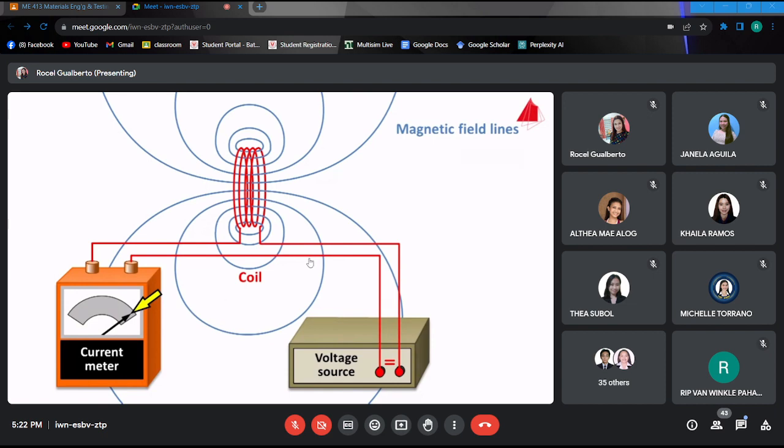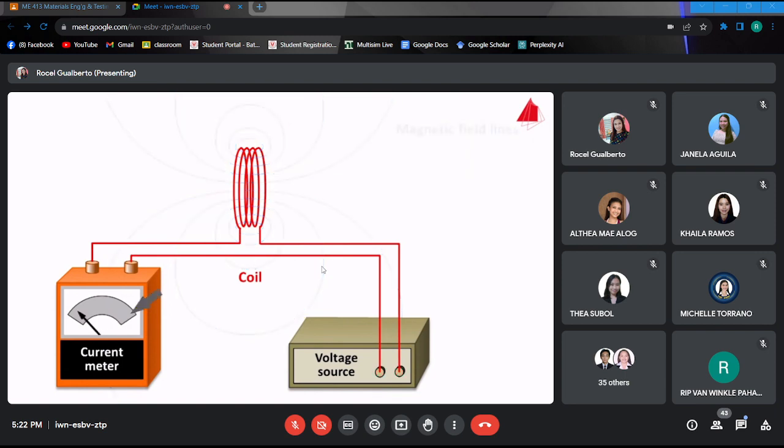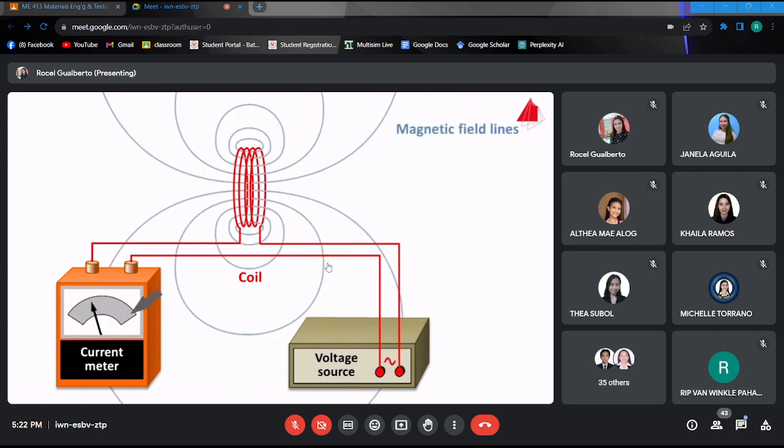The current creates magnetic fields that flow around every small piece of coil winding. The individual fields superimpose and form the total magnetic field depicted here in blue. If an alternating voltage is applied to the coil, the effective current through the coil is much smaller than when applying direct voltage. The reason for this is the alternating magnetic field, which generates a countervoltage in the coil by self-induction. The countervoltage in turn reduces the current consumption.